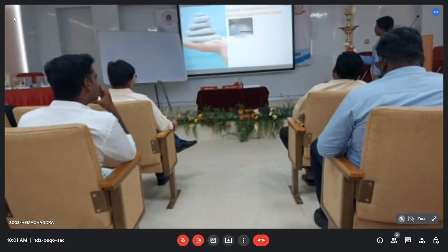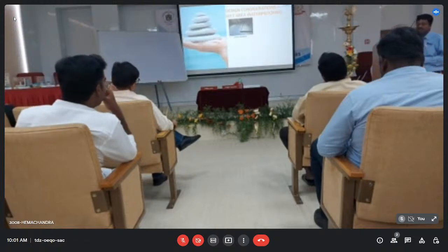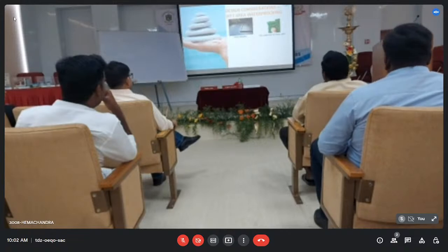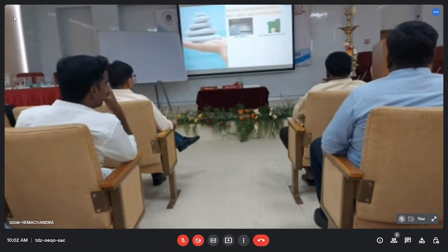What are the design considerations we have to take? One is better bonding: the product should have very good bonding to the substrate. Easy application, like brush or roller, because the room size will be very small and you cannot take very big material.